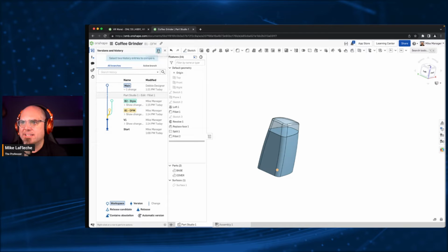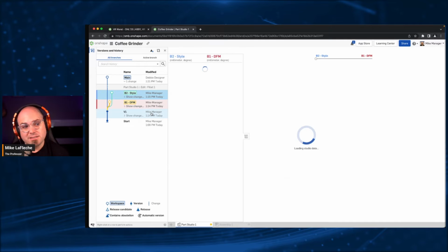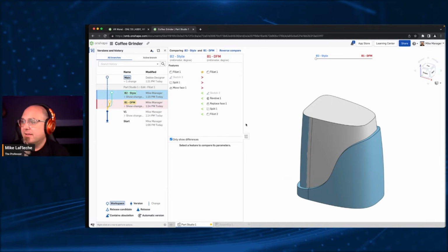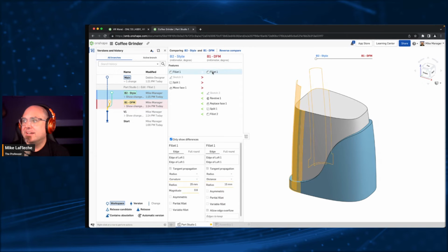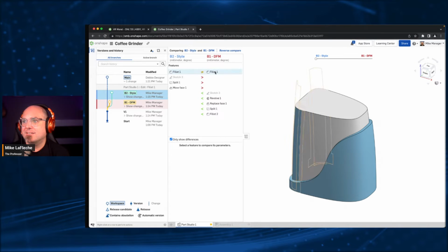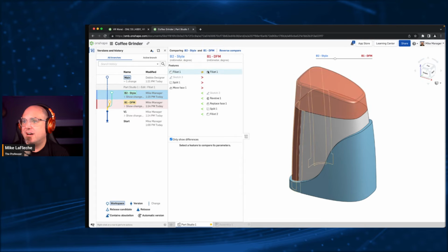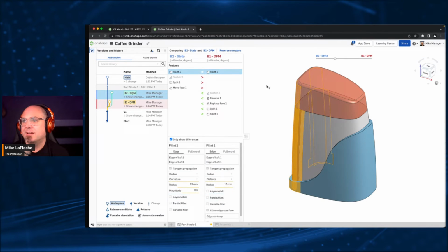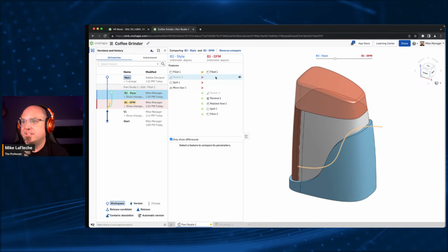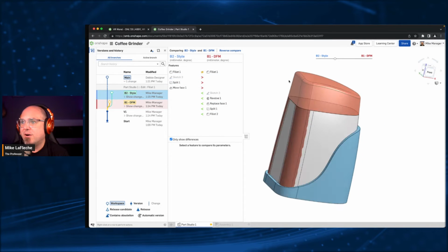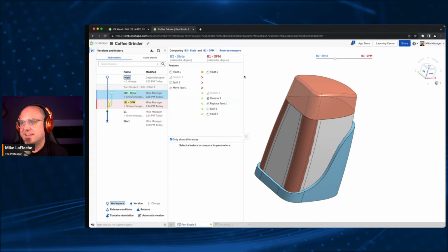But this is wildly different than what we have on the DFM branch in the style branch, right? So I can hit this button at the top of the tree here to compare this against that. So this is showing us all the things that are different between the merges, right? So we have style, DFM, we can show an animation of what is different. We can obviously see the fillets are wildly different. We see newer features and features that weren't here. But all of these situations, we have 3 situations of things that need to merge.